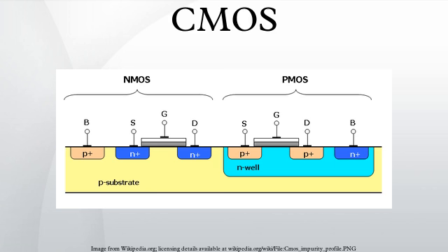Example: a NAND gate in physical layout. This example shows a NAND logic device drawn as a physical representation as it would be manufactured. The physical layout perspective is a bird's eye view of a stack of layers. The circuit is constructed on a P-type substrate. The polysilicon, diffusion, and N-well are referred to as base layers, and are actually inserted into trenches of the P-type substrate. The contacts penetrate an insulating layer between the base layers and the first layer of metal, making a connection.